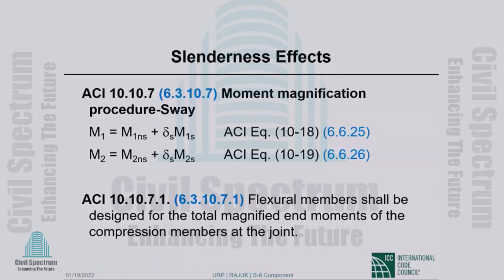But gravity loads typically do not cause appreciable side sway. There is an exception to that, however. If you have a very unsymmetric building, then gravity can cause appreciable side sway. So do not think always in terms of gravity versus lateral. Okay, so that's my advice. There are situations, not very common, of a total lack of symmetry when gravity can cause appreciable side sway.